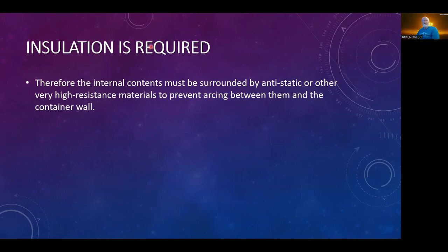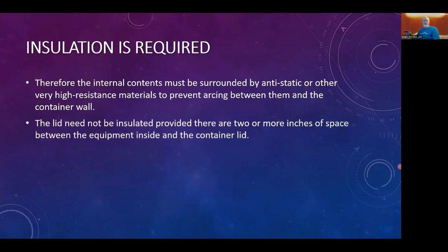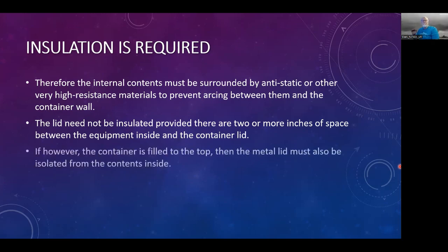Also, the internal contents must be surrounded by anti-static or other very high resistant material, preventing arcing between them and the container wall. Now, the lid doesn't need to be insulated, providing that you have at least 2 inches of space from the bottom of the lid to your devices.